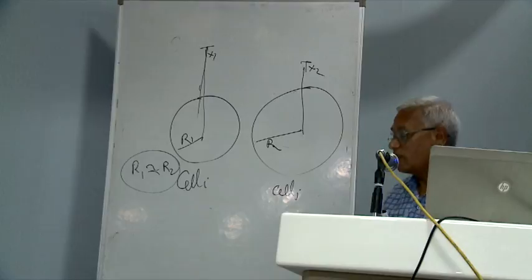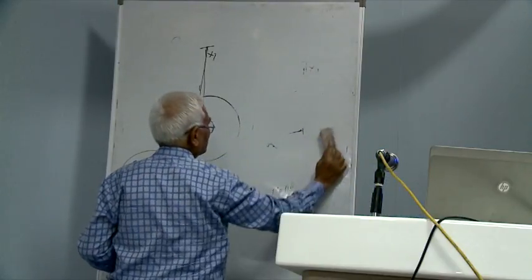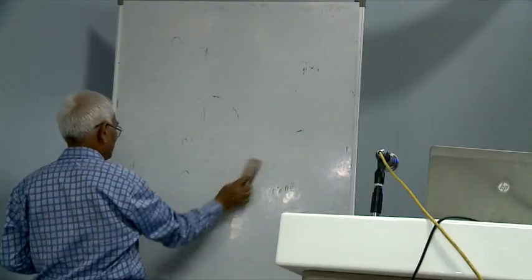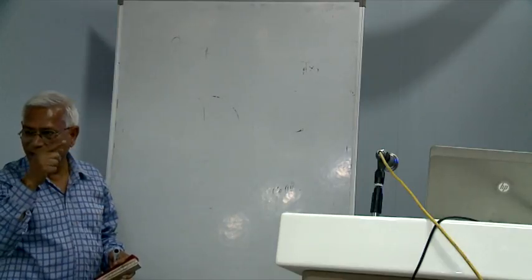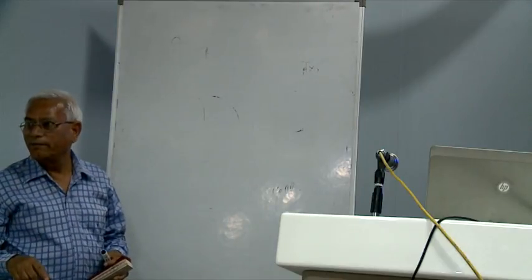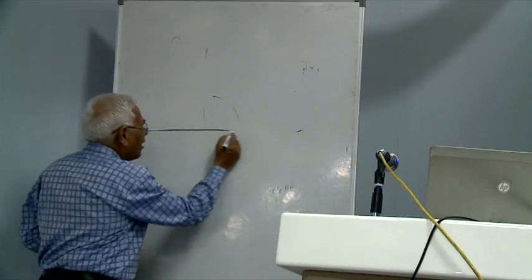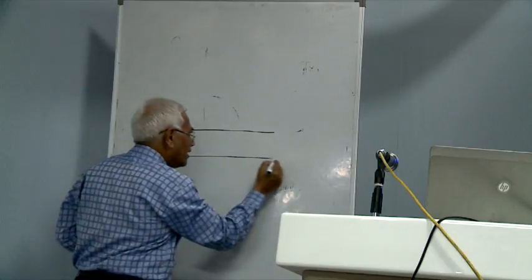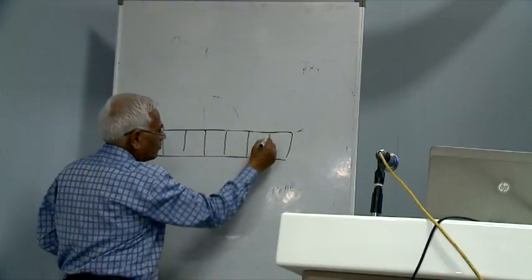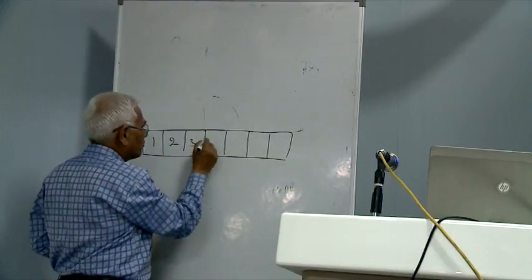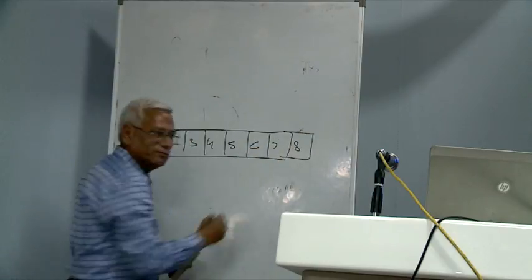Each channel has 8 slots. The channel frequency starts from 890 up to 915 megahertz, 200 kilohertz each channel. And each channel has 8 slots: 1, 2, 3, 4, 5, 6, 7, and 8. Listen.